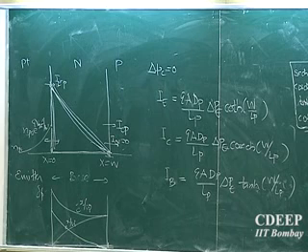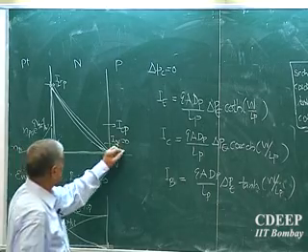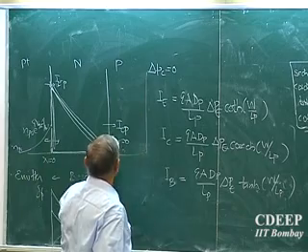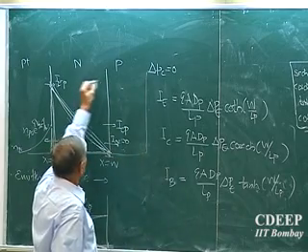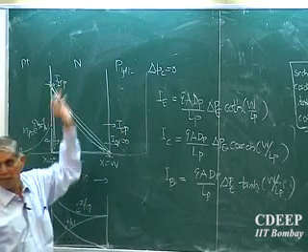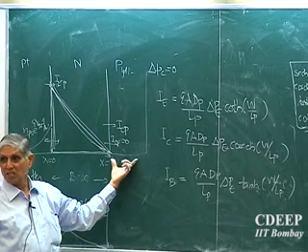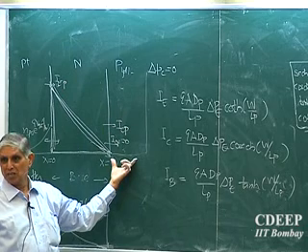Whereas VCB can be anything. It can be 1 volt, 2 volt, 5 volt, 10 volt. What is the limitation of that voltage? If this is my collector, which is lightly doped compared to the base, how much VCB I can apply will be decided by this region.